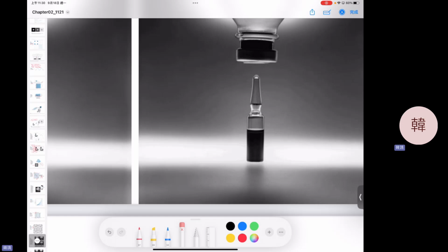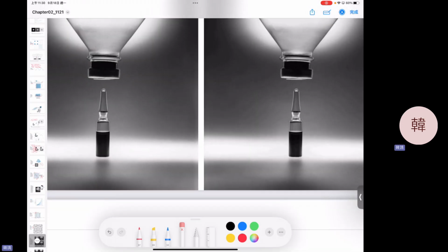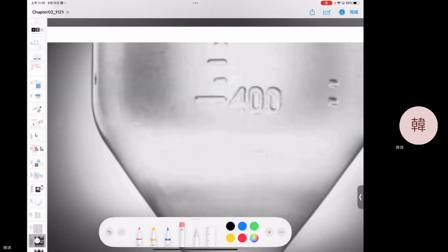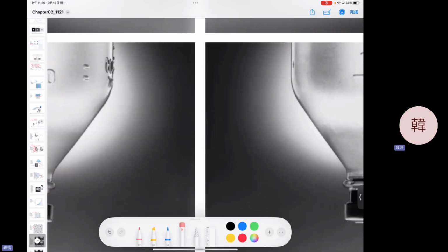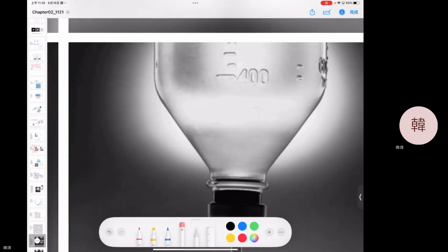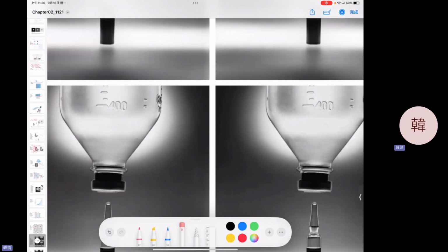But compare these two, still good, right? Still good, right? 32 gray levels. Okay? So good. That's what I told you. Your vision does not tell much difference in your image when you downsample your intensity level. Okay? The same spatial resolution, but different intensity levels.